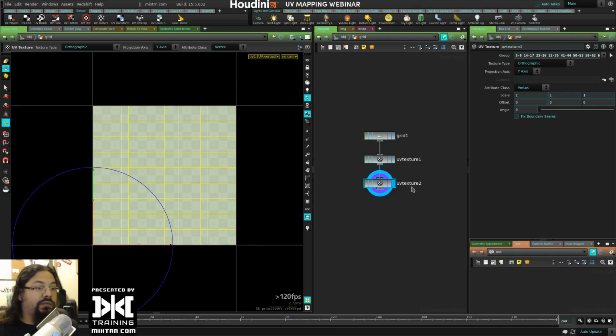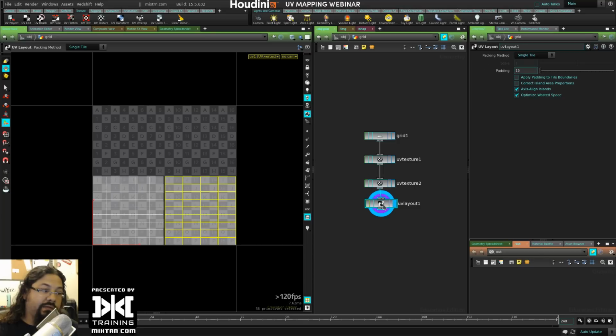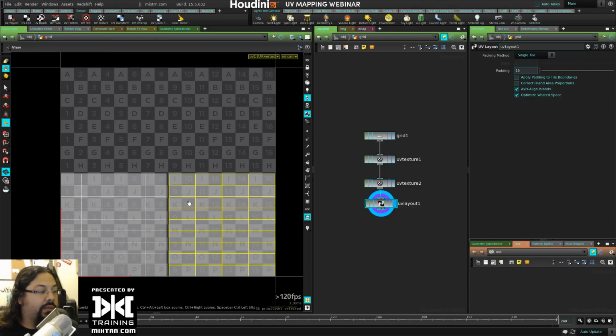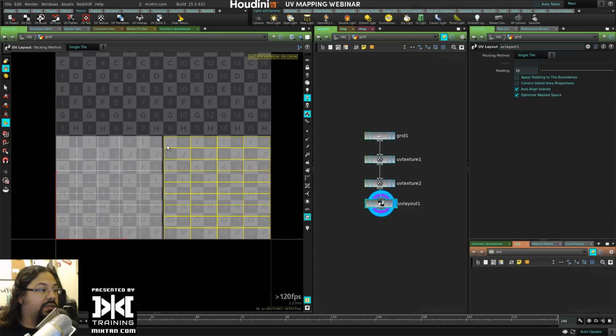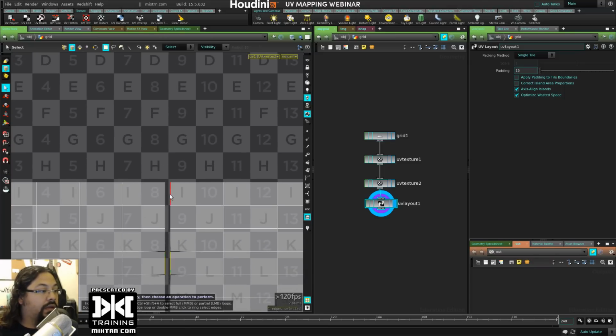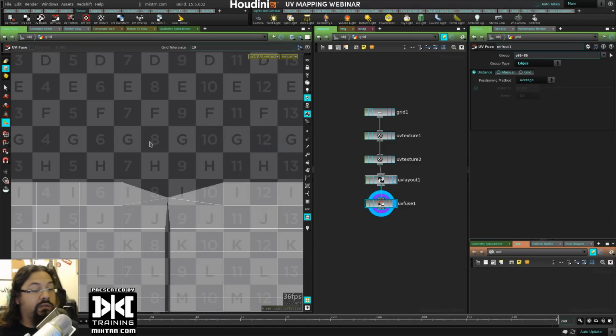Now I will have two UVs, making some UVs here. Now I want to merge some edges, right? Let's find where the edges actually meet. These two edges, I'm lucky. Let's say I want to merge some edges. We can actually just select one edge, say UV fuse. This is what works for me. UV fuse, and then it merges the edges.